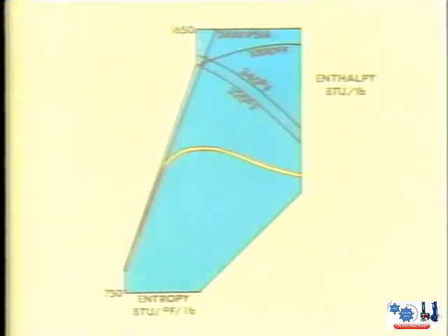If you need to know the amount of superheat in steam at 2,450 psia and 1,000 degrees, you find where the pressure and temperature lines intersect and see that the intersection falls between 320 and 340 degrees Fahrenheit. Taking the average, you can determine the amount of superheat, which is about 330 degrees. Now, what we've just shown you is general information that can be found on the Mollier diagram or in more detail in the steam tables.